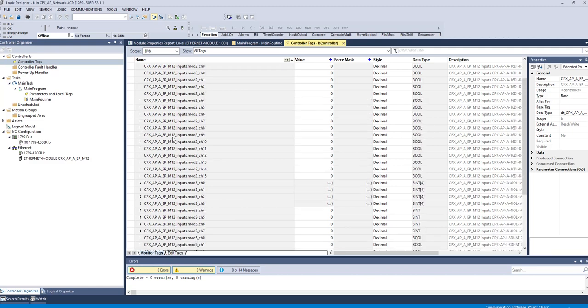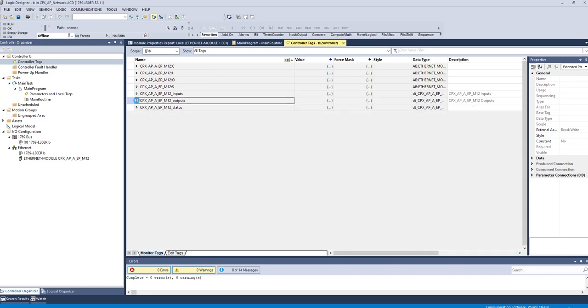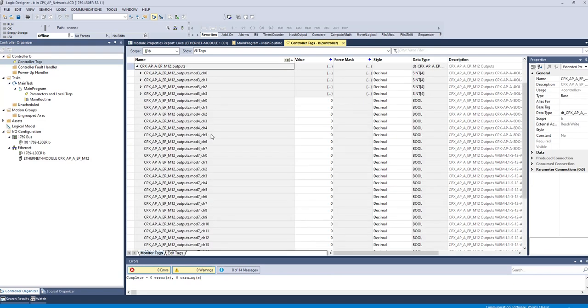The same can be seen here on the outputs. I'll run through it a little quicker so we don't spend too much time. Here's your I/O link master. Then here's your 8 digital output module that we had. And then we come down here to the valves. A digital output module and a valve manifold are both bools. So it puts this in very useful data types for us.